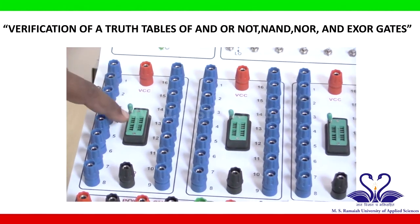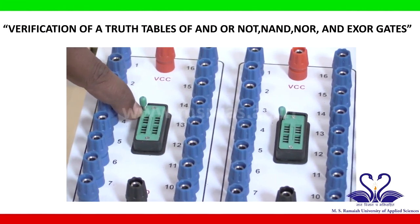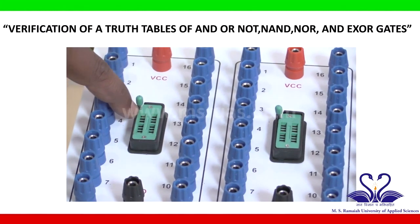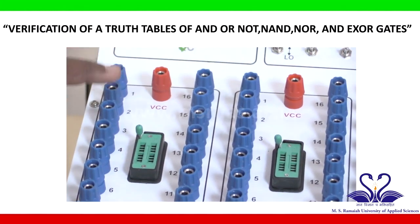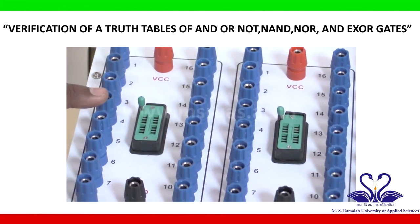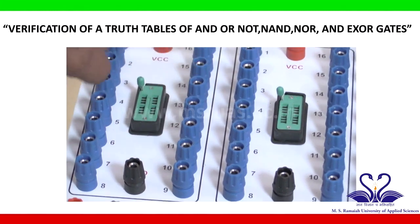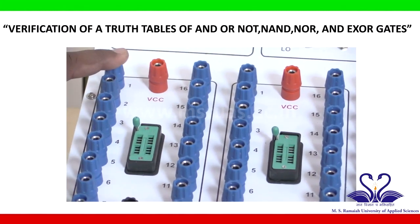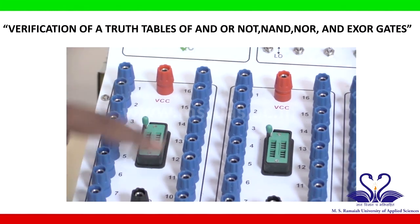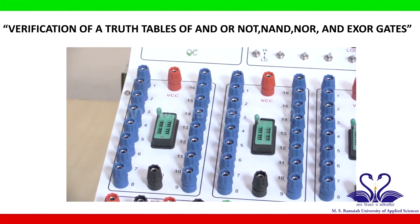And whenever you mount the IC on this, pin number 1 should be inserted in the first slot. Whenever you insert pin number 1 here, this terminal will be pin number 1, pin number 2, pin number 3, pin number 4, pin number 5, pin number 6, 7, 8, 9, 10, 11, 12, 13, 14, 15 and 16. And for every IC we need a ground and a VCC, which is also provided in this kit. So this is a ground and this is the VCC.